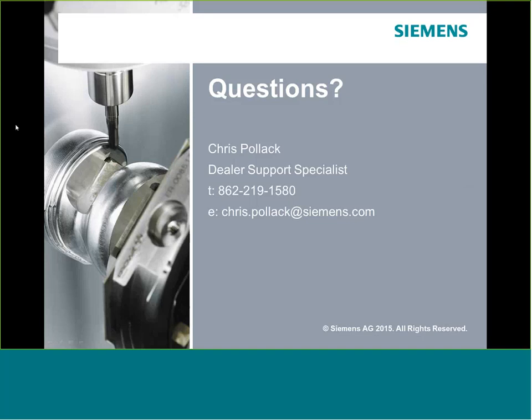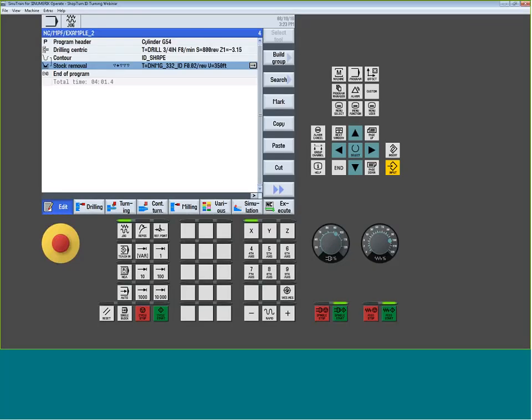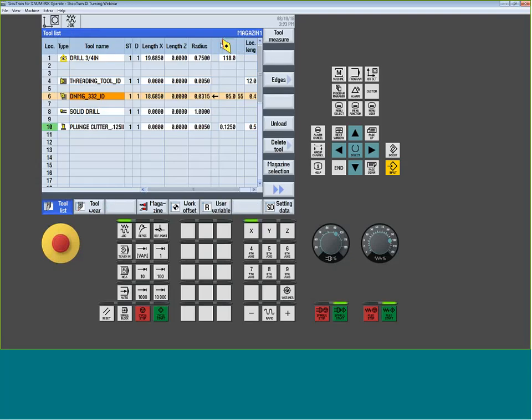Does the Siemens have a way to avoid gouging the tool? Yes. You have full insert checking and gouging active based on you creating the geometry of the tool. When we built this tool, we told it the relief angle and our insert angle so it can back calculate where the backside of the insert is.